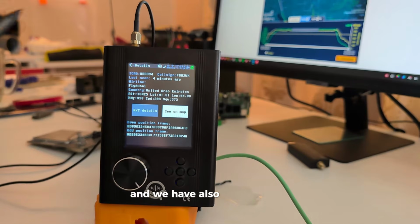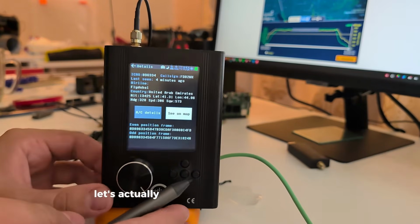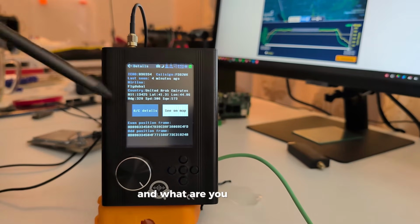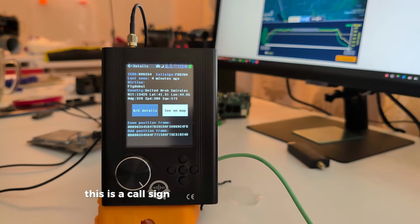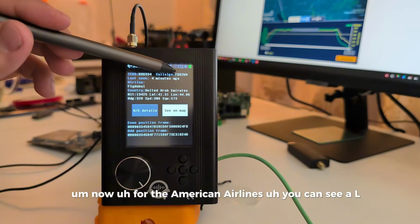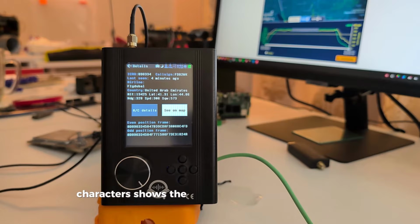And we also have the call sign, you can see here on the right of the ADS-B. Let's actually fix the HackRF position a little bit. And what you are seeing is FDB2WK. This is a call sign or a flight number. Now for American Airlines, you can see AAL. So the first three characters show the company name. In this case, it is probably flydubai.